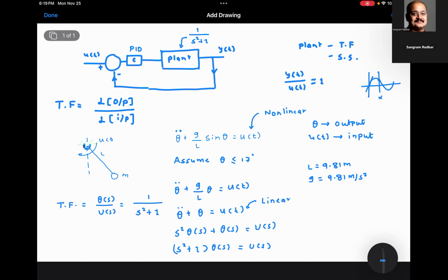This is something similar to gain scheduling, but I'm going to show you how to do linearization using MATLAB numerically, because you will use the exact same approach if you want to control your robot. Because your robot control equations, the robot equations are very long. You cannot manually linearize those. You cannot manually design a controller.